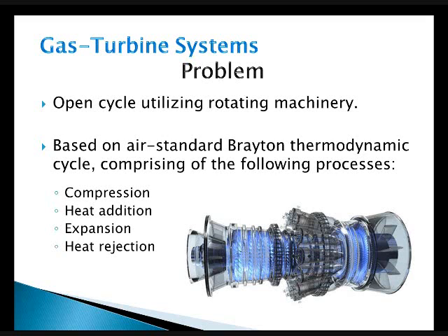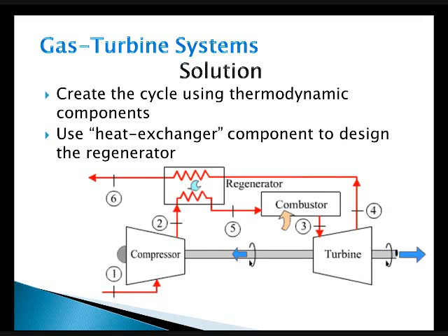So here I'm not going to go into a very fancy example of that. You were just looking at an electric power plant. So you have a compressor and a turbine, and then you have a regenerator that heats up the air before it enters the combustion chamber. You could just as easily have intercoolers in the stages of the compressor. You can have reheating in the turbines if you chose to do that, and see what happens to your efficiency. You could use any kind of heat exchanger you want from the ThermoFlo components, or design your regenerator.